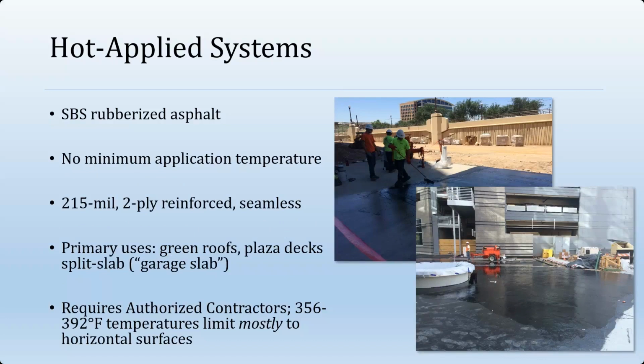It's a 215 mil 2-ply reinforced system, which basically has no seams. And its primary uses, most notably, are green roofing, plaza decks, and split slab garage slab type decks. But these systems' manufacturers require authorized installers.